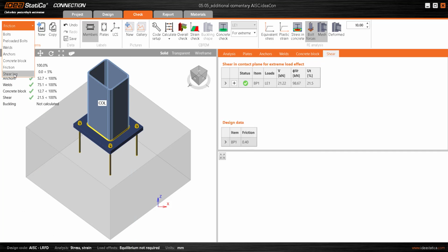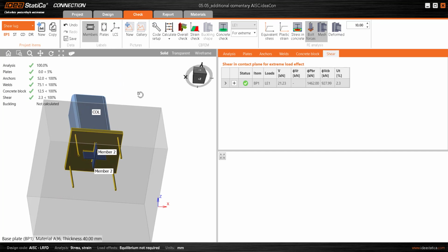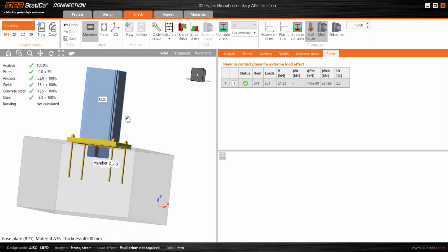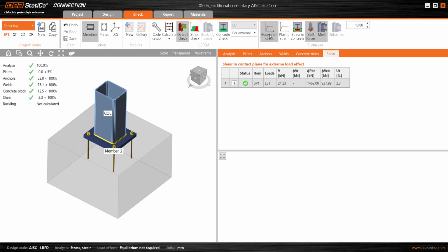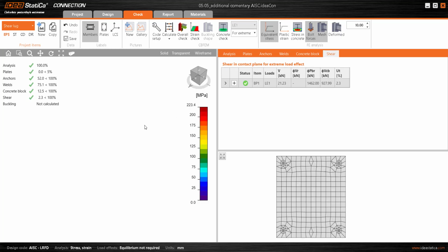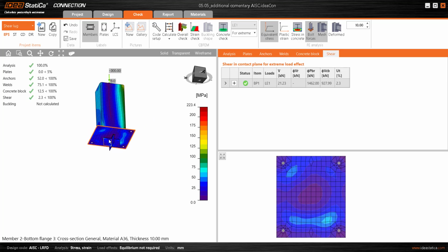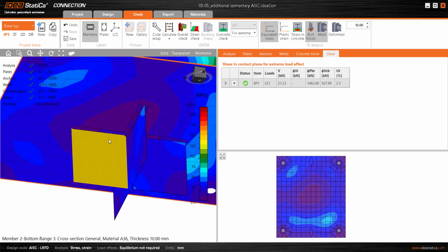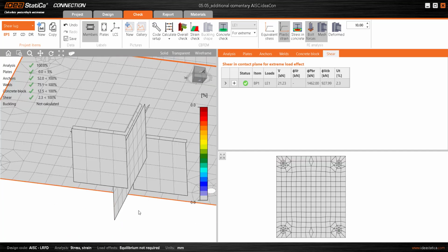Lastly, we'll look at the shear lug. One of the interesting details is that, in this case, we've used a cross shear lug, which is fairly typical. The software checks the lug using finite elements, using the same criteria that's used for the other plates, given that the lug is modelled explicitly. The welds of this lug are also modelled. Consequently, what we need is for it to satisfy checks via the plastic deformation criteria that we've already used for other elements.